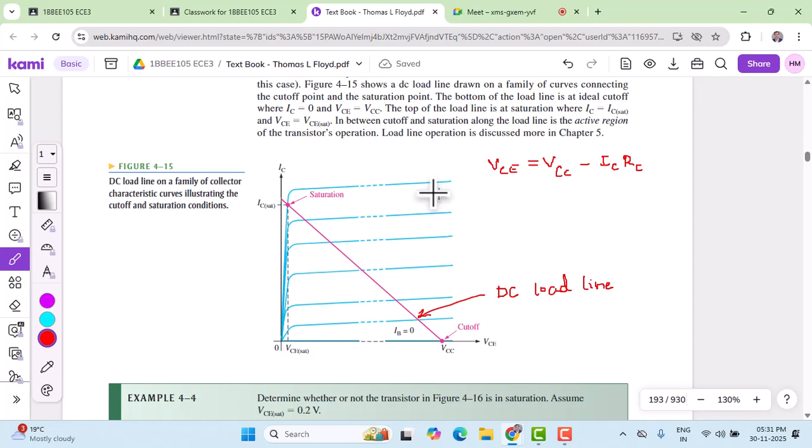The formula for PD max is the product of the collector emitter voltage and the collector current. This rating is important because it decides what the collector emitter voltage and the collector current must be for the safe operation of a transistor.